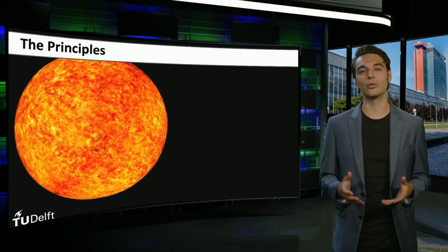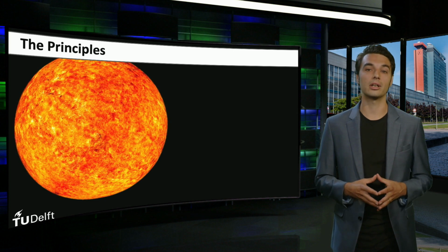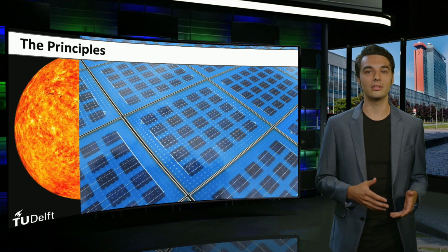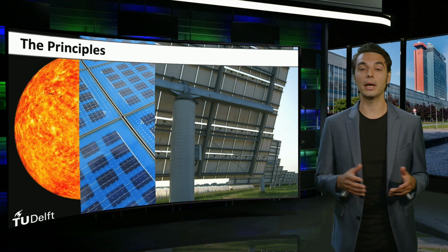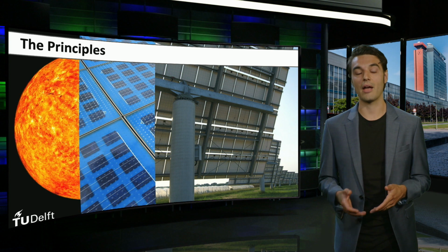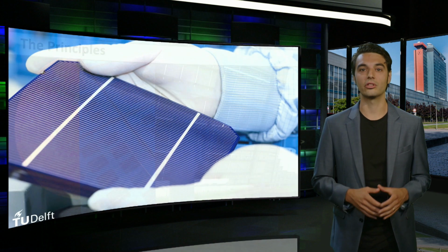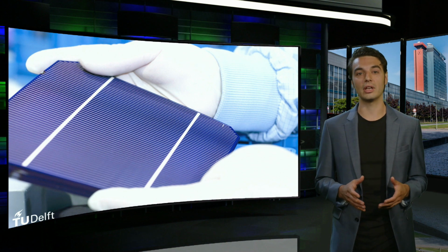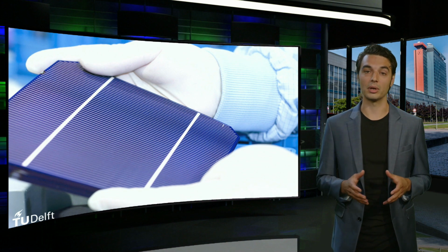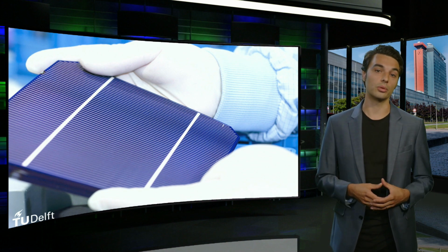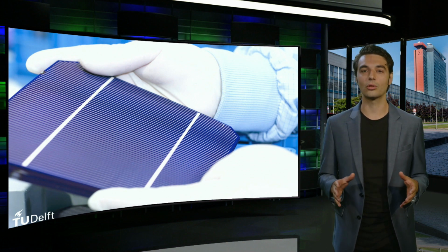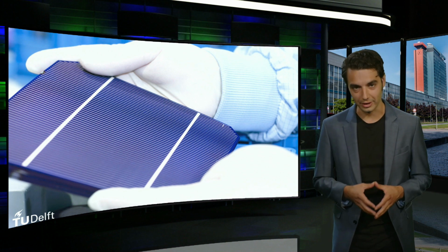In photovoltaic energy conversion, the light emitted from the sun is absorbed by the semiconductor materials in the PV panel. The semiconductor material converts the light's energy directly into electrical energy. The panel is connected to an inverter that converts the DC output of the solar panel to AC power and facilitates a grid connection. Since there is only a single conversion step in photovoltaics, from light to electrical energy, losses in the PV system are limited to the PV panel conversion efficiency, transport losses in the wires and cables, and the losses in the electronic components such as the inverter. Later in this course we'll discuss all the losses that occur in a solar cell in detail.